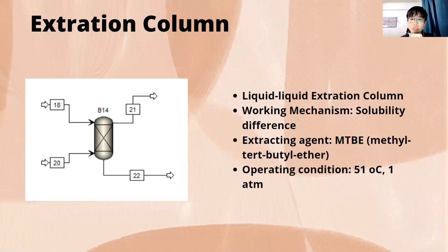The solvent used in this context is MTBE. MTBE has been identified as the best solvent for extraction of acetic acid from water due to its high selectivity, low density, and low heat of vaporization. The extraction process works at a temperature and pressure of 51 degrees Celsius and 1 atm respectively. Next.